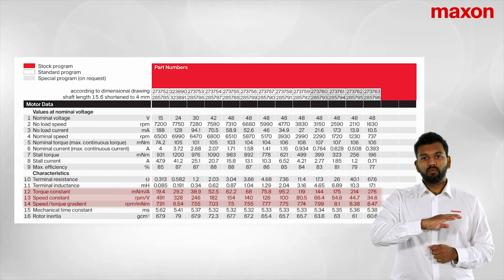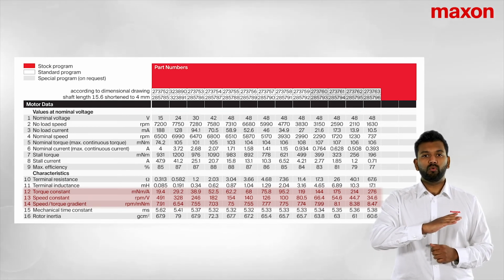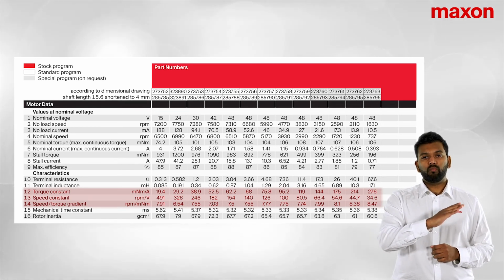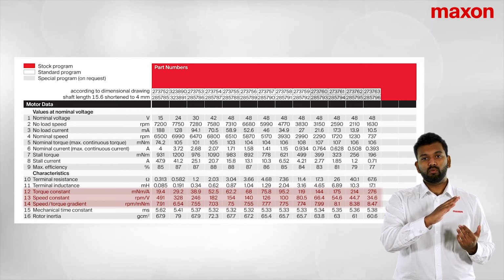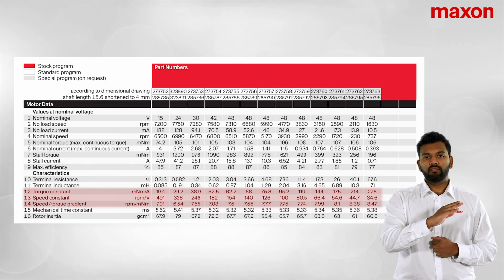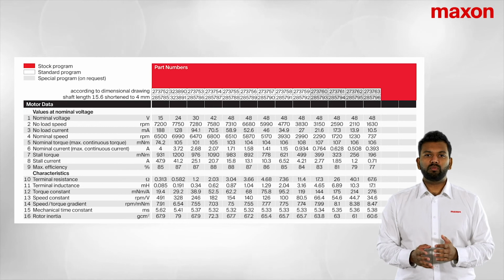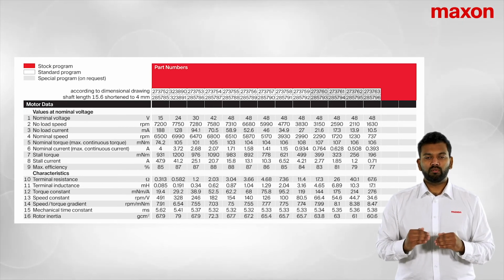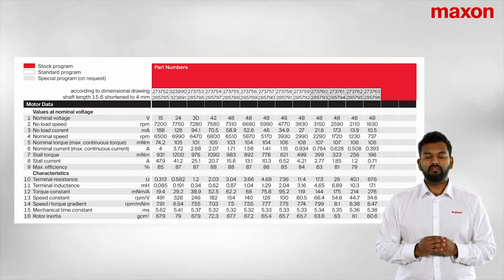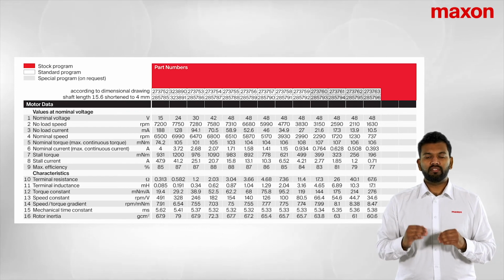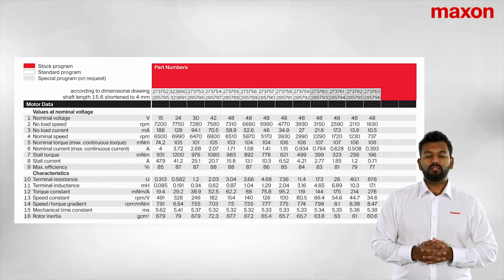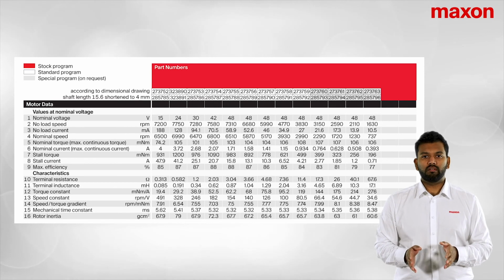So throughout all the windings, you'll notice the torque will be more or less the same. Whereas with one that's steep, you'll notice that the torque will differ throughout that range. So as you go up in the winding range, it will differ. So this is something to consider if you were going to take multiple motors throughout a single range, say the RE35, and you wanted all of them to have the same torque. So this is quite useful in those kind of scenarios.